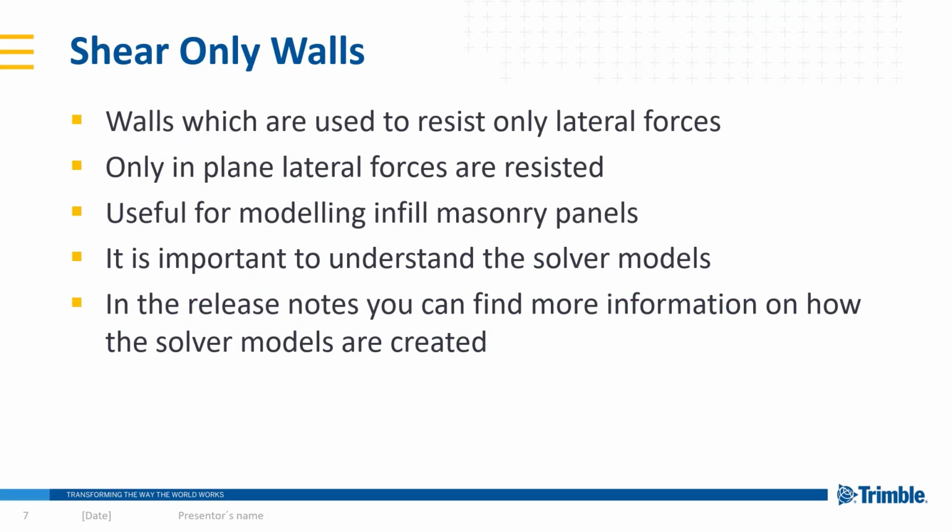So the final subject under modelling today is shear only walls. These are walls that are used to only resist lateral forces in the plane of the walls. The most useful time you would use these is for panels that are there to resist only lateral forces, such as infill panels or infill masonry panels, as an example.